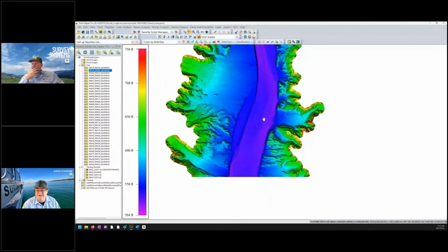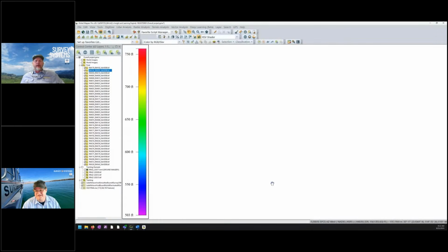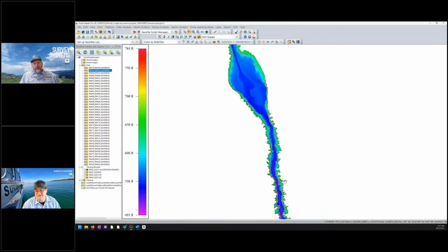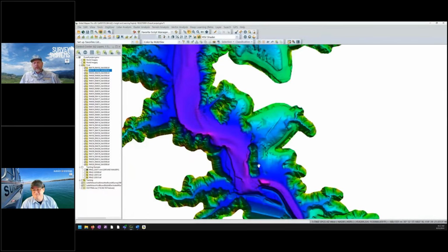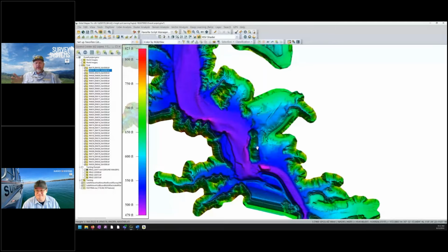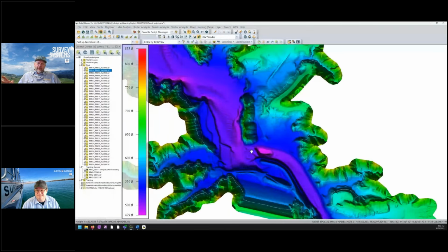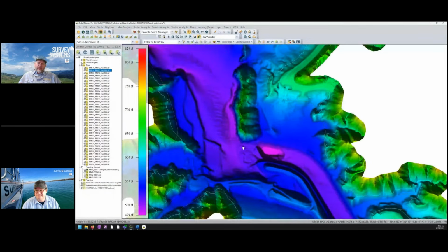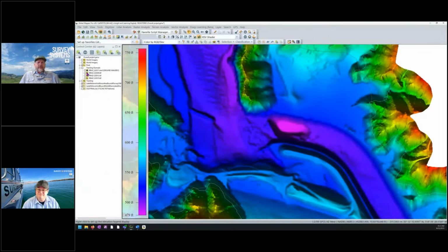In hydrographic surveying, you're kind of a long-tailed cat in a room full of rocking chairs when you get up into those shallow areas. And so that red and green line, it's white in this instance, is a great benefit to us. When we're using topo bathy LiDAR, it gets some coverage down into that shallow water, from the shoreline down. It depends on the clarity of the water what kind of penetration they get. On Lake Mojave, for instance, they got consistently 20 and sometimes 30-foot returns. But if we can keep the boat in a safe area and collect data up there, that allows us to do that.